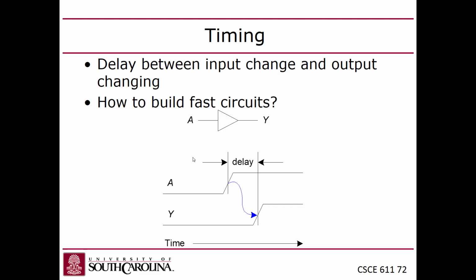So when I say charge, what am I talking about? Charge means I want a wire, and I want to transition a wire from a 0 to a 1. I have to charge it. So I have to physically move charge carriers to do that, and that takes time. And then if I want to discharge, it's the same thing. It takes time to discharge. So it takes time to drop a signal from 1 to 0.